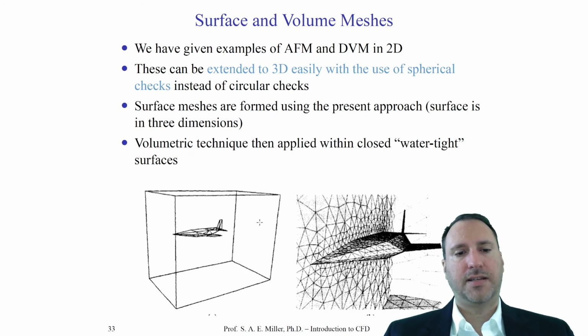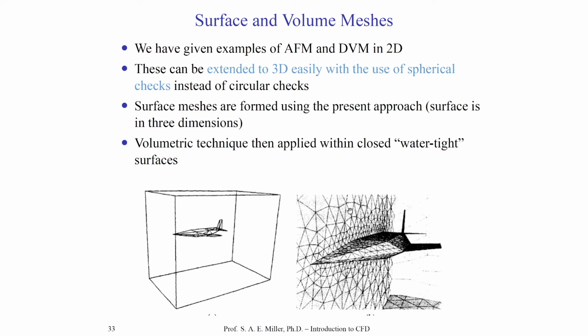So you can see in this example in the lower right, one interior mesh, which might be on the wall for a symmetric boundary condition, and on the surface of this particular vehicle, you can see the vehicle has triangular elements, and the interior of the domain will be tetrahedrals. All these elements have to have closed form connectivity so that the mesh is so-called watertight, meaning that there are no holes or gaps or tears or two elements with missing connectivity.